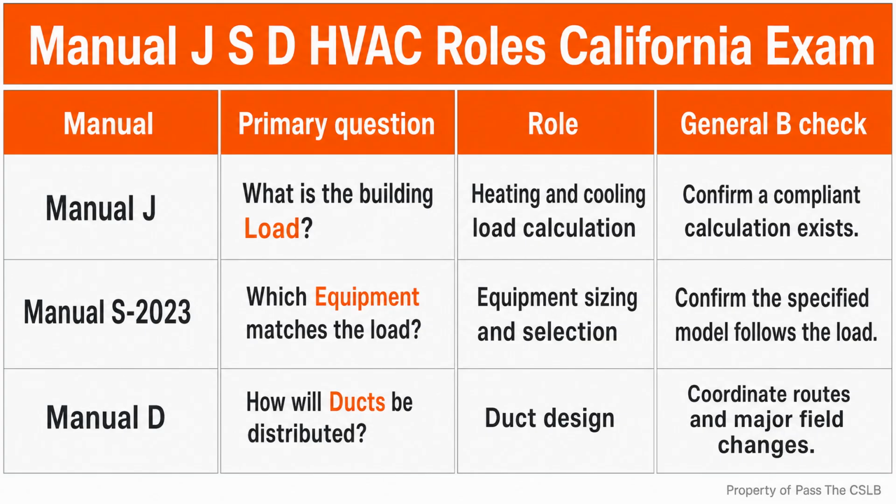California standardizes important design inputs, so the load calculation is not manipulated by choosing convenient temperatures. For sizing calculations covered by the source material, the indoor heating design temperature is 68 degrees Fahrenheit. The indoor cooling design temperature is 75 degrees Fahrenheit. Those are calculation inputs. They are not a promise that every occupant must set the thermostat to those temperatures. I treat them as standardized design baselines used for sizing.